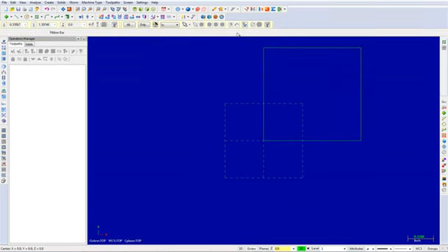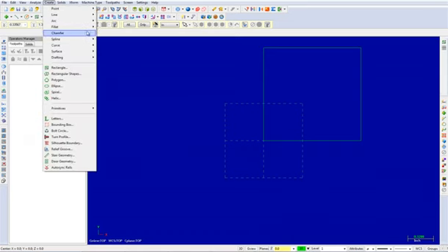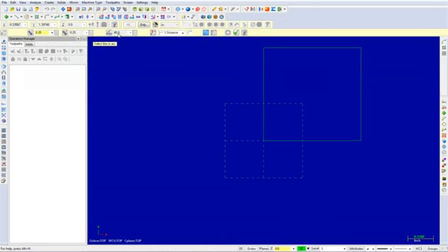Next, we will create a chamfer. In this step, you will create a 1/4 inch by 45 degree chamfer. Select Create, Chamfer, Entities. From here, enter a distance of 0.25 in the ribbon bar and ensure that the chamfer style is set to one distance and that trim is enabled. Select the following two lines to create the chamfer. Once complete, select the OK button to exit the command.